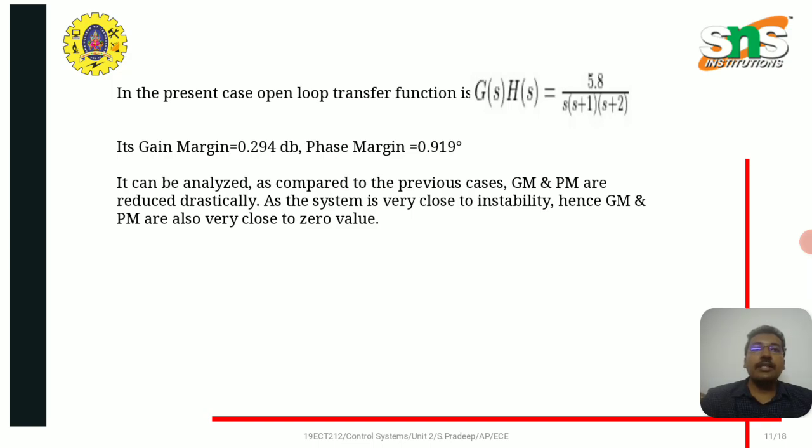It can be analyzed, as compared to the previous cases, that the gain margin and phase margin are reduced drastically. As the system is very close to instability, the gain margin and phase margin are also very close to zero value.